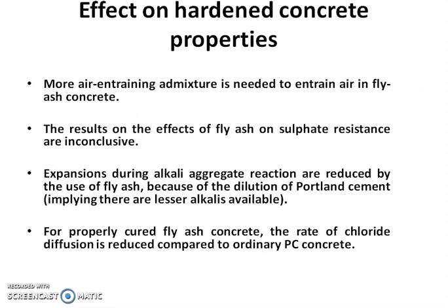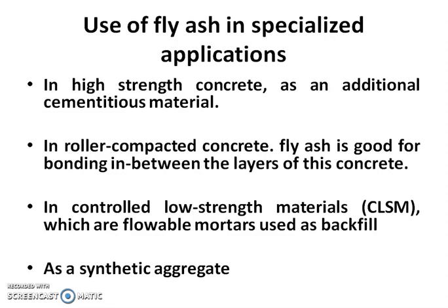More air entraining admixture is needed. The results on the effect of fly ash on sulfate resistance are inconclusive. Expansion due to alkali aggregate reactions is reduced because of this fly ash. This is the effect of fly ash on the hardened concrete properties.